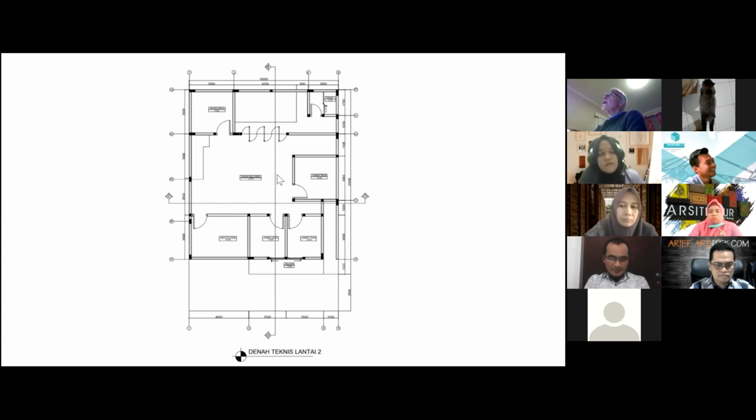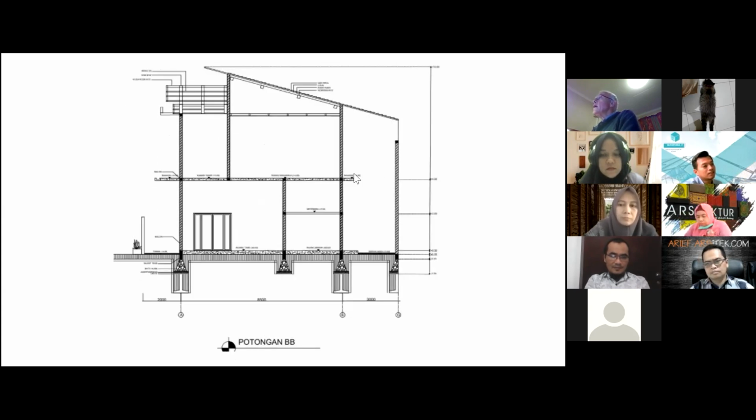Let's look at this point here in section B. See, here's the gap between the floor diaphragm and this confined masonry wall. Now, the other problem is that this wall really needs to go up to this level so that we can have tie beams tying the building together to create a diaphragm at this level. So the earthquake forces can move sideways through bond beams or tie beams and then go down the vertical walls.